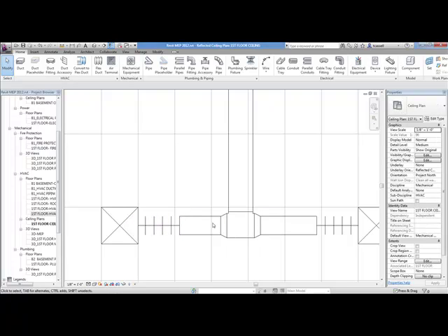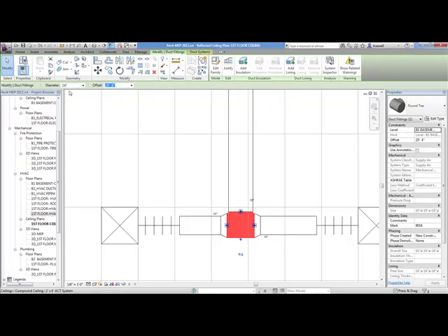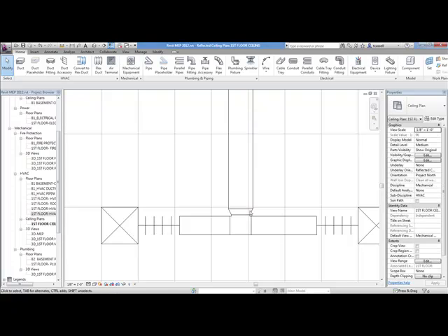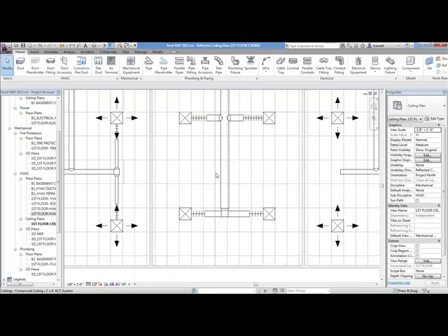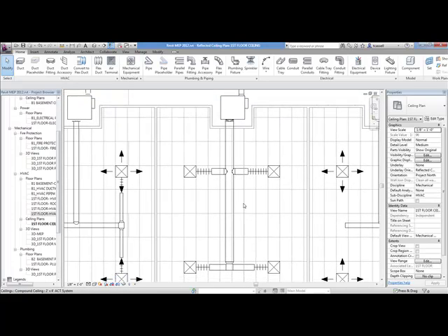Smart enough to take the reducer and move it to the T. Well, actually, I want the reducer here coming into the T. I'm going to make that a 12-inch T. There's the reducer there. And then there's a lot more options, such as I could have a reducing T. I just don't have one put in right now. So that way the T would accept the 16-inch coming in, and then it would allow 12-inch going out. So we now have a complete closed system.